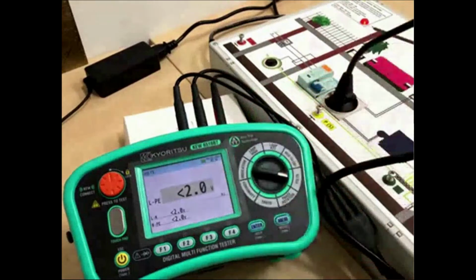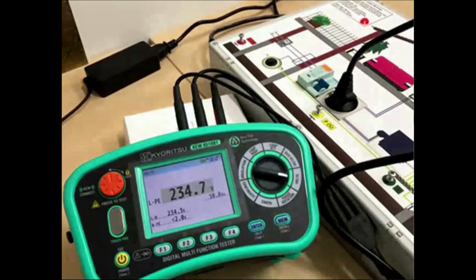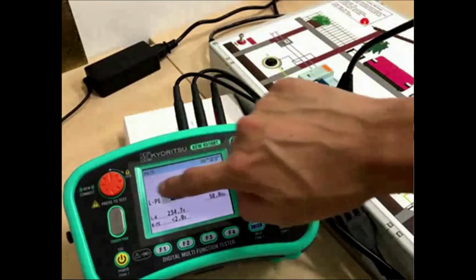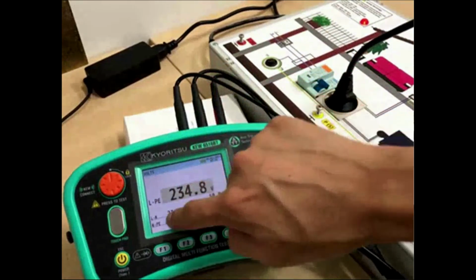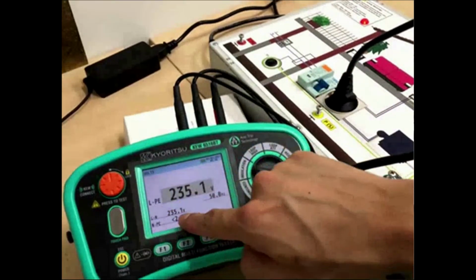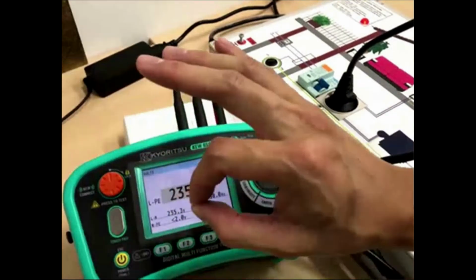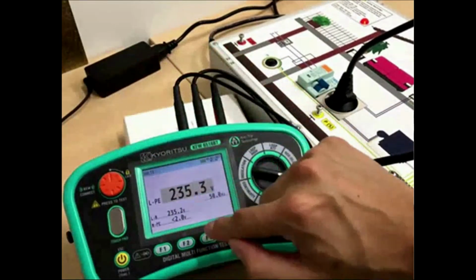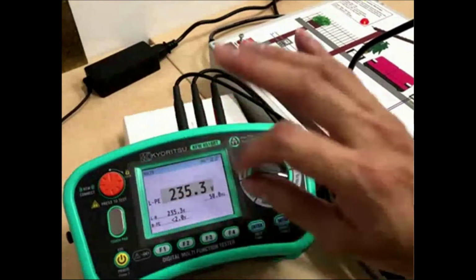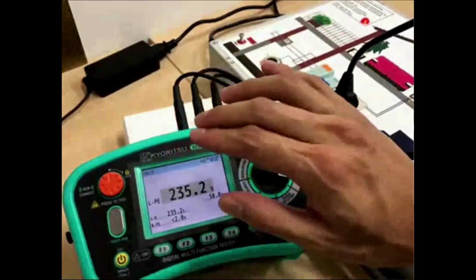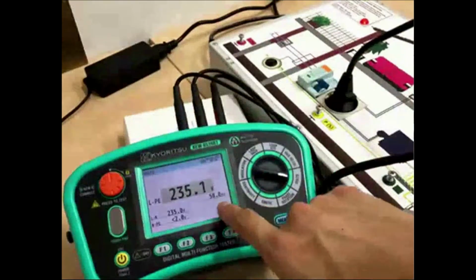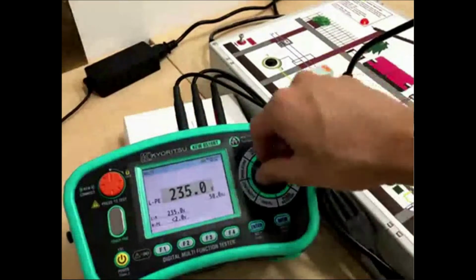Okay, so now you turn on. So you saw 230 volt. Live to PE is 230 volt. LN, live neutral, 230 volt. N to PE normally is 0, normally below 2 volt. You all understand this one? Live, neutral, and earth, you all must understand. So this is the operating frequency.